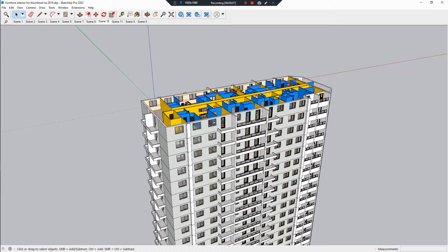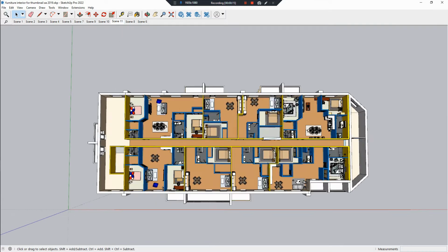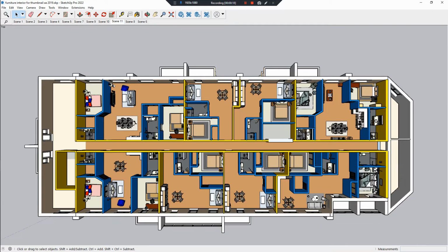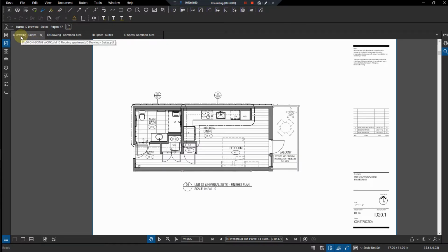So here is a cutoff, and let's do the floor and tile measuring here plus baseboards, and we are going to be focusing on just this apartment here, or rather this floor. So this is a typical apartment floor, and we have multiple types of flooring. We have some tiles here, and carpets, etc. So we need to measure the quantities accurately so that we can build a proper spreadsheet for the flooring contractors. So let's start over here.